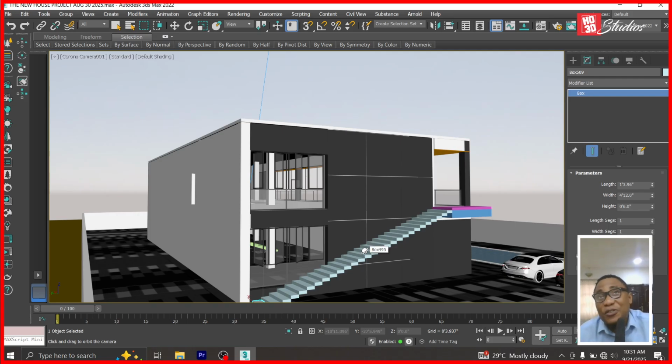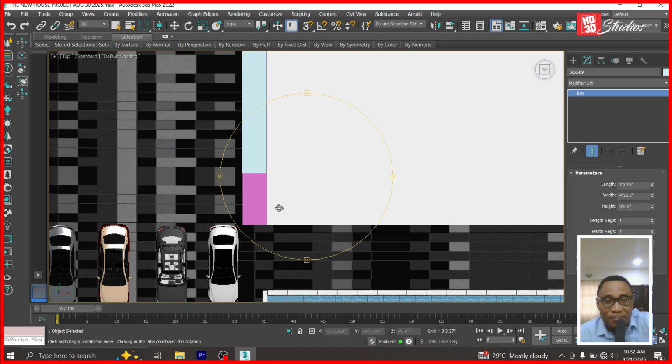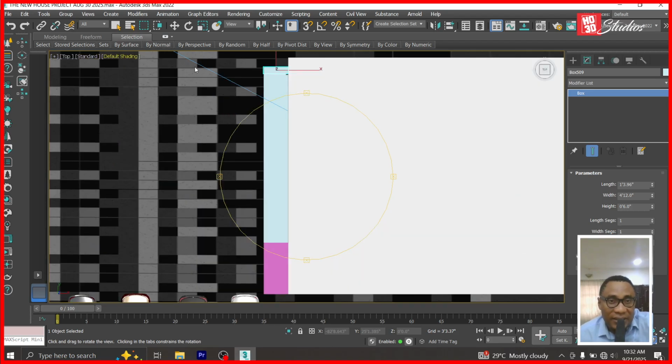Now, what they often recommend is that the run and the rise combined should give about 18 inches, which means if you have a 6-inch rise, you should have about a 12-inch run. But in this case, because it's a luxurious house, I just thought a 12-inch run would be too small. So now I made it 16 inches. And there you have it.